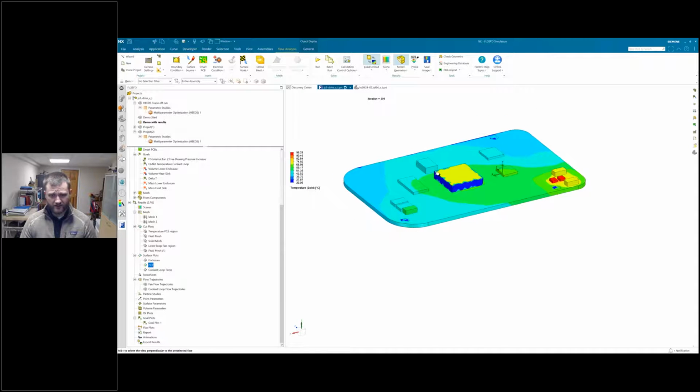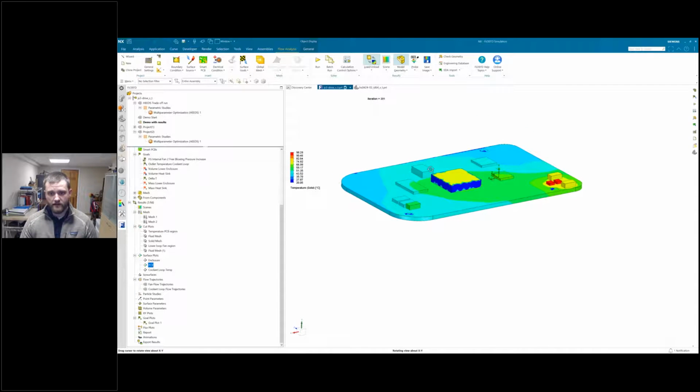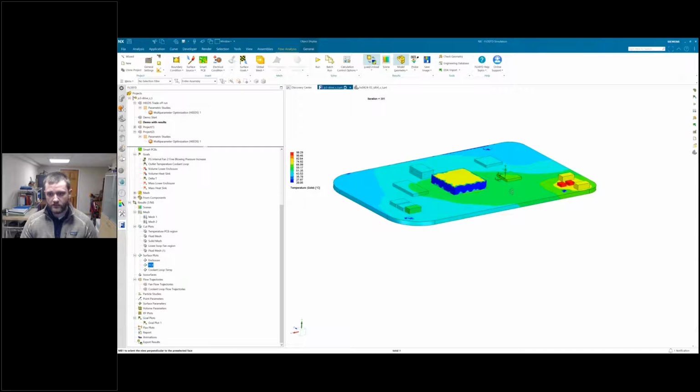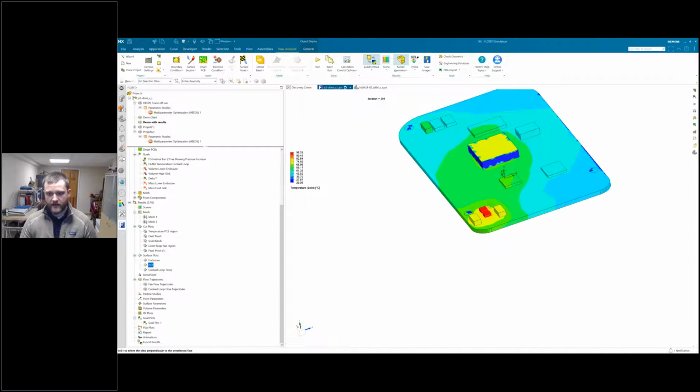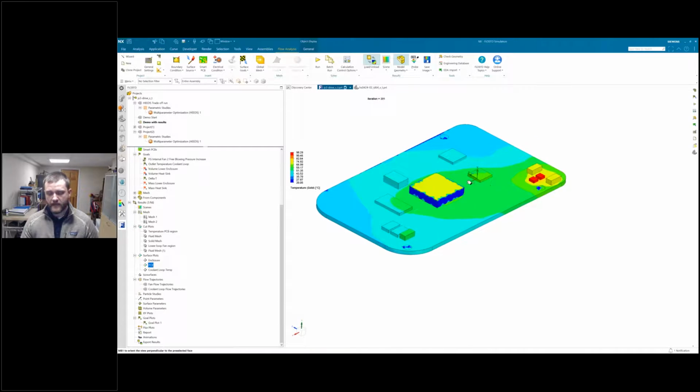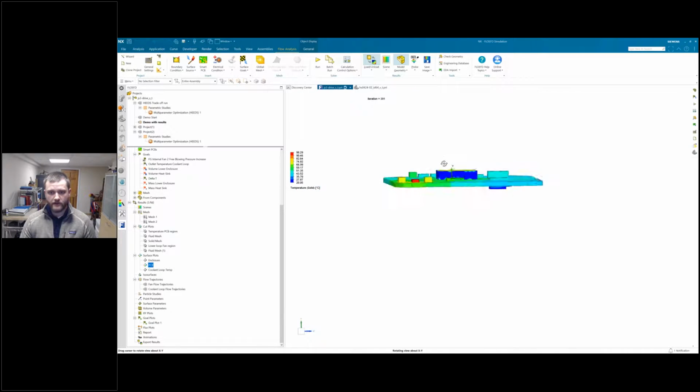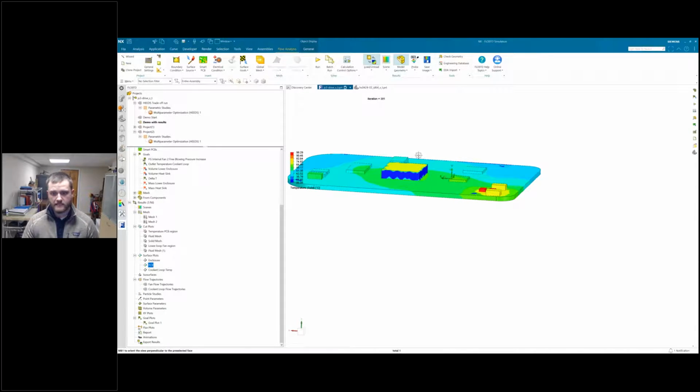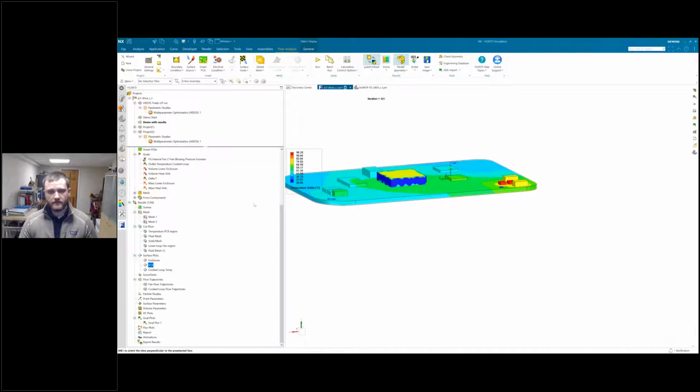You can see here that our PCB overall is looking really good with fairly low temperatures. We do have a kind of high temperature on these two chips, and maybe we want to change to our cooling plate that has an outcropping that touches those components to cool them off a little bit more, because 98C is maybe a little bit high. So that kind of shows that.